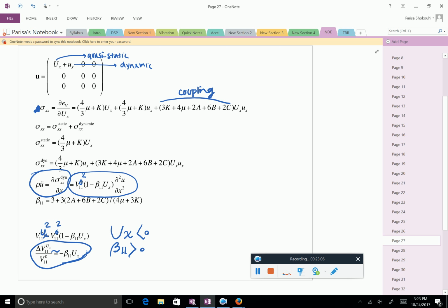But then people interpret this from the macroscopic point of view. They say, okay, the reason for that is that cracks close. So basically, this is a macroscopic view of how that crack closure changes the elastic constants. That's the macroscopic view of why it is happening. That's how I see it. But it is only valid when you are in the elastic region. When you go past the elastic, the whole theory falls apart.